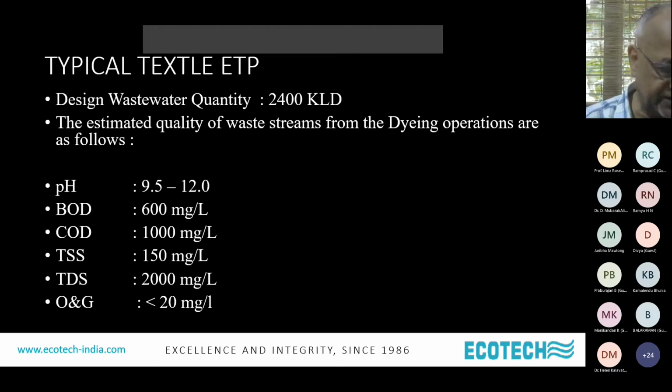The COD to BOD ratio is a measure of the biodegradability of the wastewater. Typically, for domestic sewage, the COD to BOD ratio is 1.8. That is the standard we use for comparing biodegradability of other wastes. For instance, brewery wastewater, the COD to BOD ratio is 1.2 to 1.5. That means it is very readily biodegradable, much more biodegradable than domestic sewage.